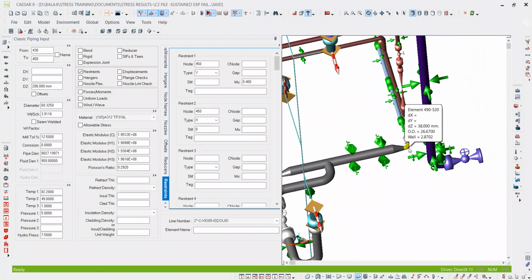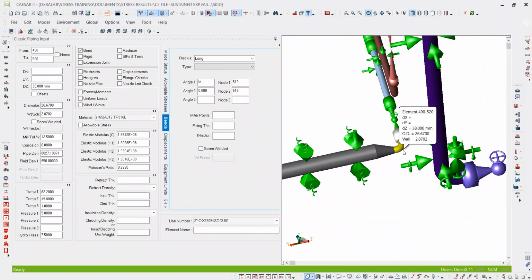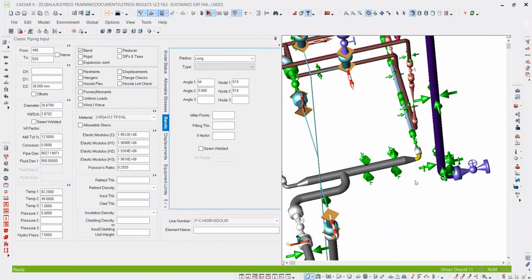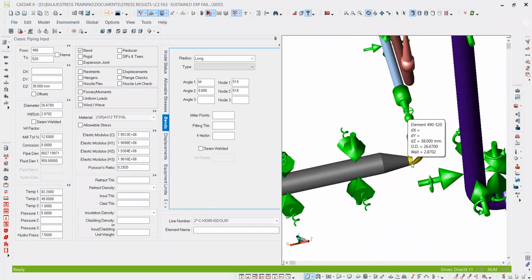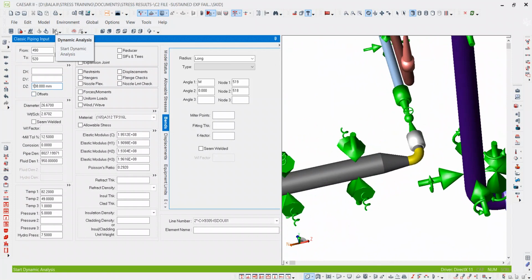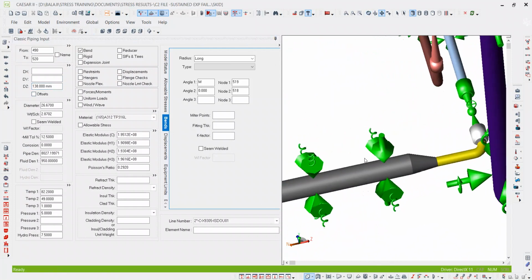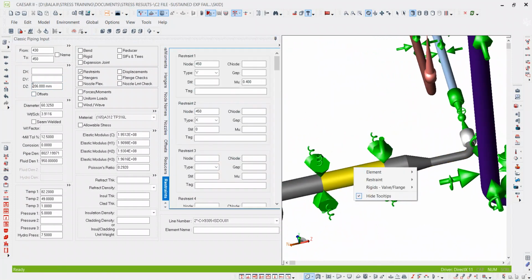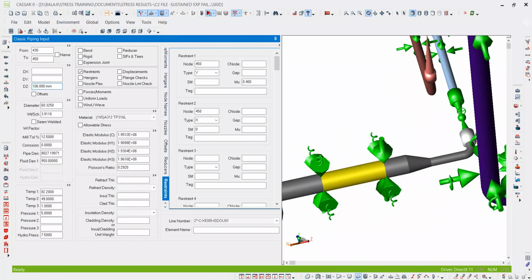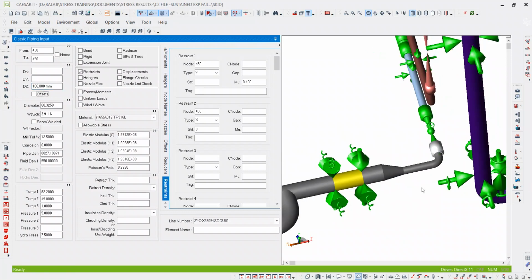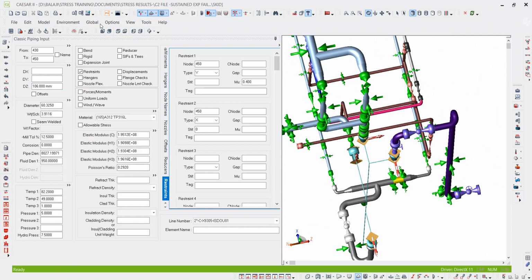So what we will do, like what we have done for the PSV lines, we'll try to add a spool after the reducer. Maybe it may cause failure. So I'm going to add 100 mm here, and reduce that spool because the overall length remains the same, 106. Okay. Now just run the system.